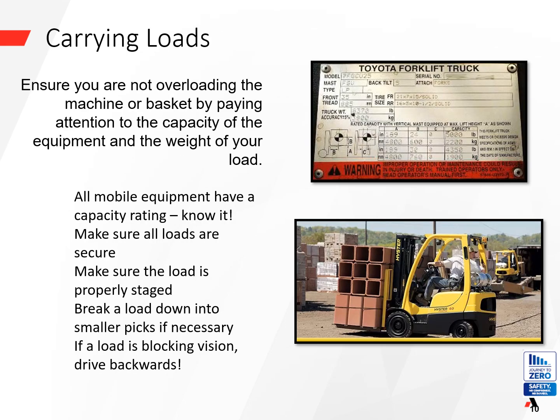Load handling. Be mindful of equipment capacity and load weight to prevent overloading. Know and adhere to the equipment's capacity rating. Secure all loads adequately to prevent movement during operation. Arrange loads properly for safe handling. If necessary, consider breaking down large loads into smaller ones. When a load obstructs your view, reverse the equipment to maintain visibility.